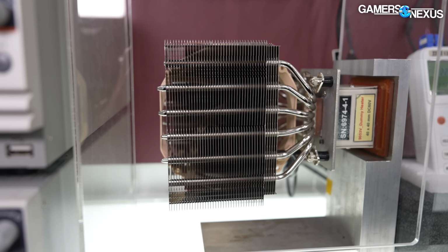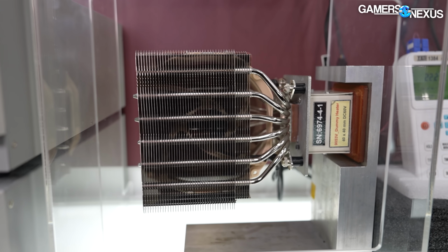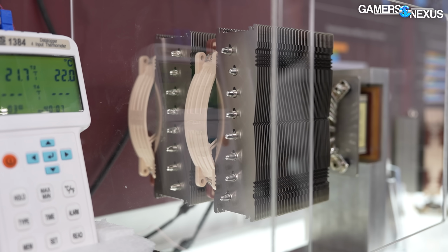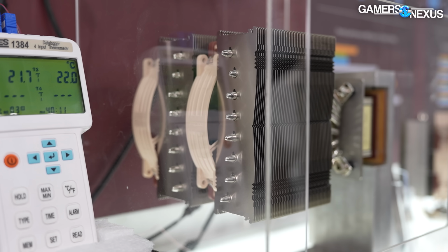The heatsink, from a heatsink design perspective, you want to go the other way around. Yeah. You want to pack as many fins as possible. You want to maximize fin surface area, but not only that, you also want to maximize fin count. Because especially the leading edges of a heatsink fin is where the heat transfer is the highest. So when you look at the heat transfer rate plotted across a heatsink fin, you will see that it's highest at the leading edge. And then there's a boundary layer built up as flow goes along the fin. And that boundary layer is like aerodynamically insulating the laminar flow. So you will have heat transfer dropping off the longer the fin is. So just making the fin longer and longer and longer, it will help, but it will give you diminishing returns. So ideally you would have extremely tightly packed short fins. But that creates a lot of resistance.